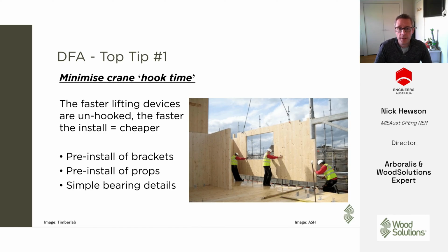So the first tip is minimise the hook time. The faster you can get the crane unhooked and going to pick up the next panel, the cheaper it'll be. So simple things like pre-installing brackets or pre-installing props on the panels, simple bearing details so that you can just drop elements onto each other is so much faster.